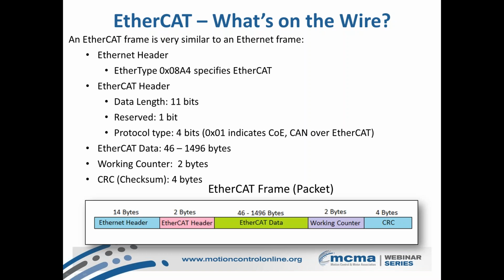In one case, the master will simply tell the drive what position I want you to be in, in encoder counts. What's your I/O status, and what's the drive status? So are there any errors on the drives? And so that's literally 12 bytes that are being sent down the line, and those are the only 12 bytes that slave is concerned with. And then that packet will contain that bit of information for each drive.